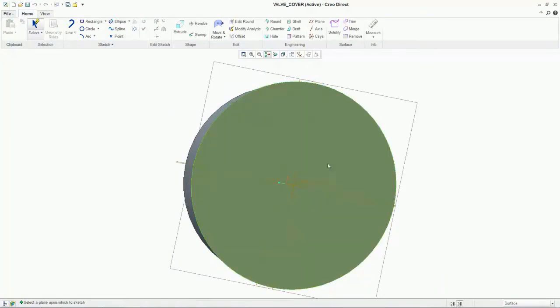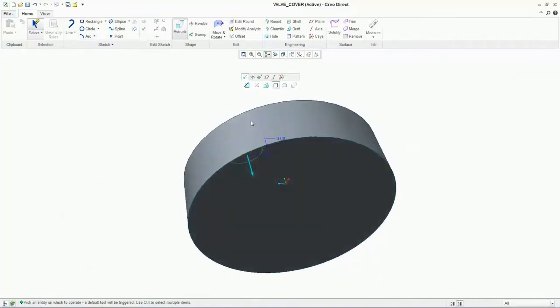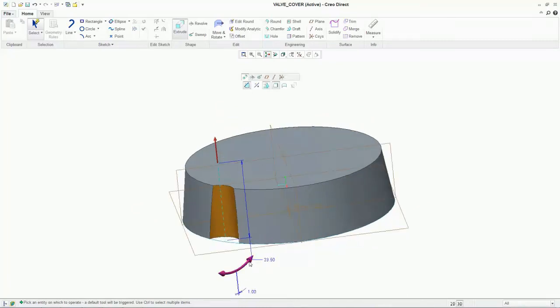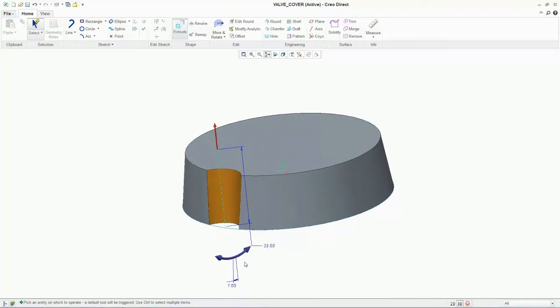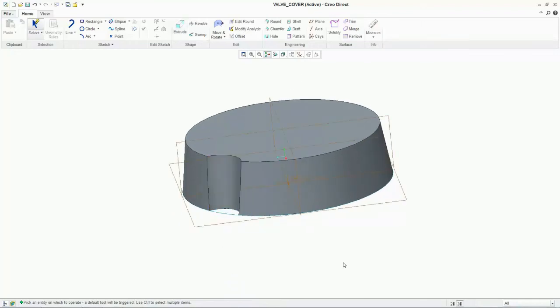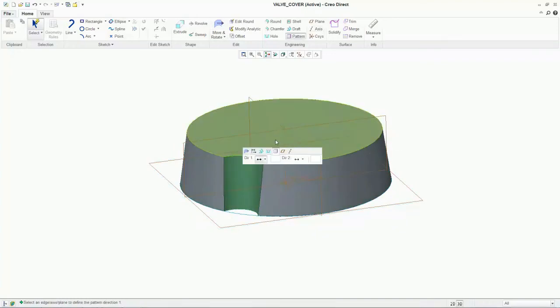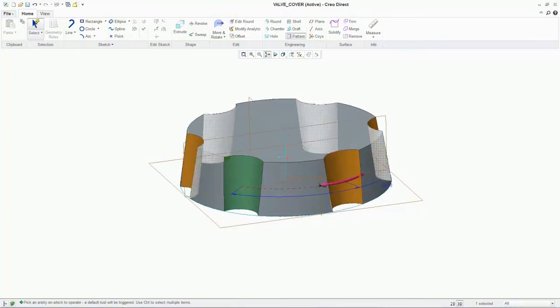It is incredibly easy to add sketches or extrusions to an existing 3D part. Seamless switching between 3D solid view and a 2D sketching plane, followed by a quick extrude in the negative direction, results in a cut. A quick taper to match the shape of the cover, and we're ready to repeat the initial bevel geometry as a pattern. By defining our axis as the vertical center of the cover, the initial extrude can be patterned and rotated around the outside of the cover while keeping complete control in the hands of the user.